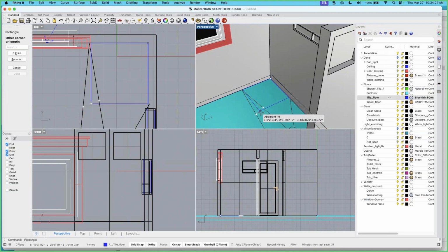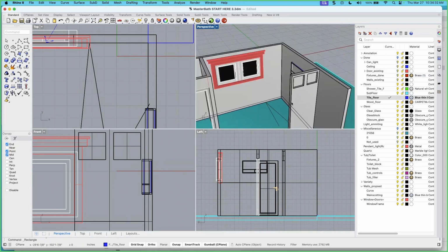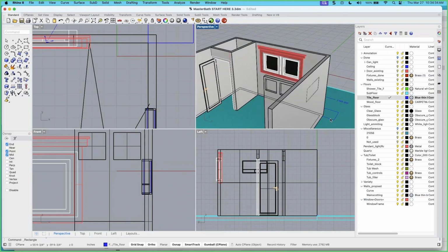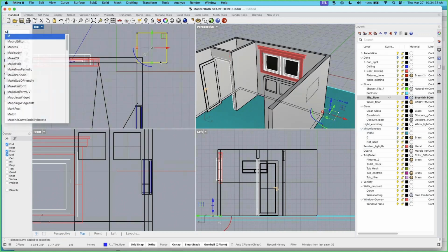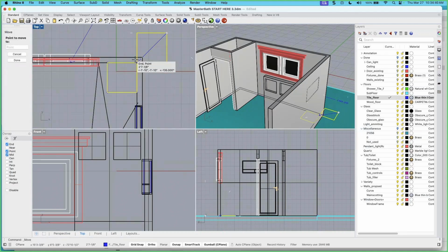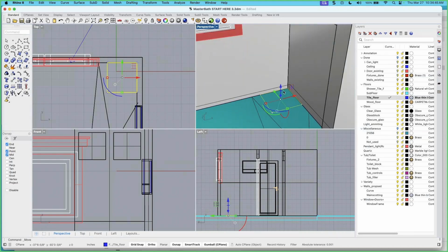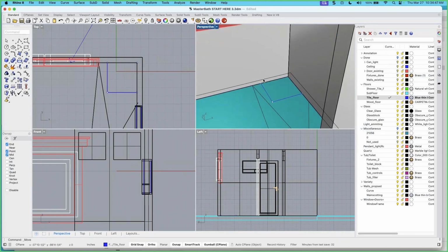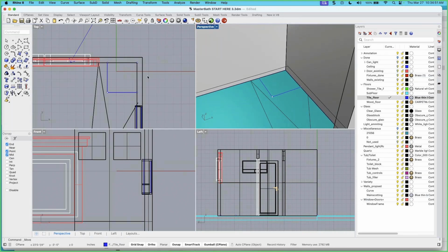I actually want it to be a little bit smaller, so I'll type in 22 for the length and the width. And when I do that, it pops out over here, which really wasn't where I wanted it, but I'll go ahead and move that with the move command back. Now, if I were a little more careful and I typed in -22, it would have ended up here.